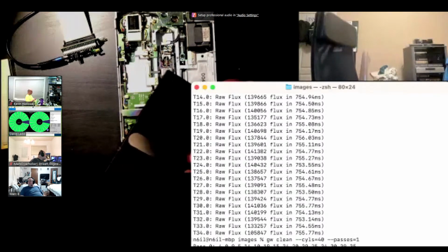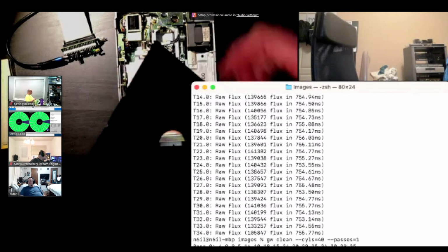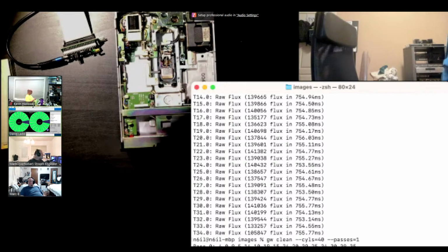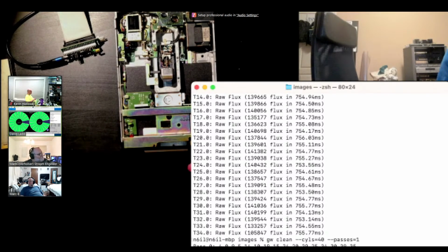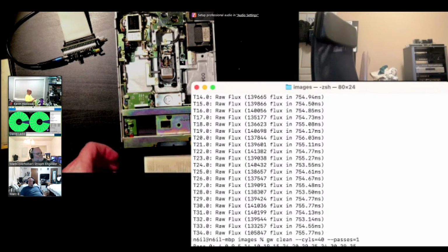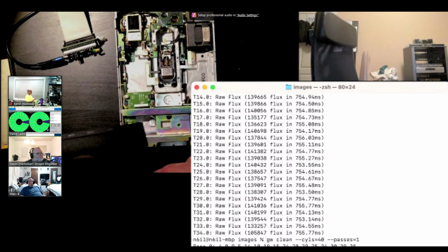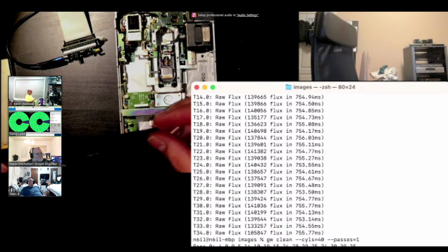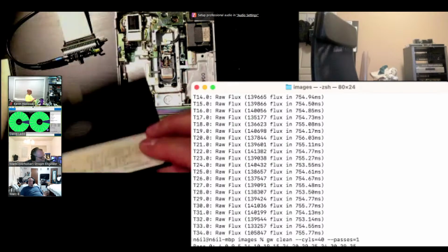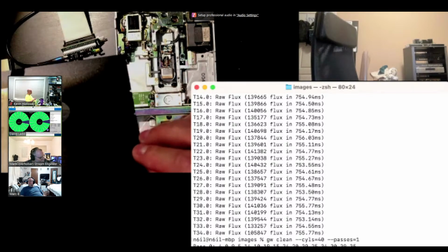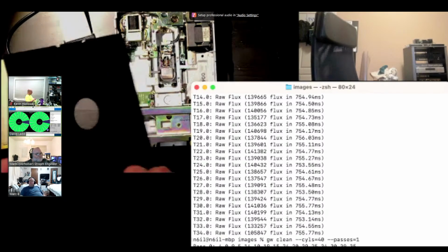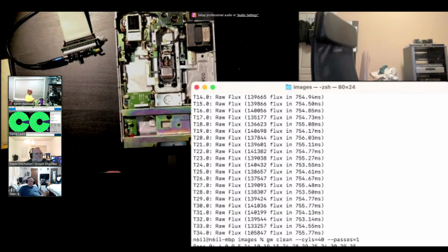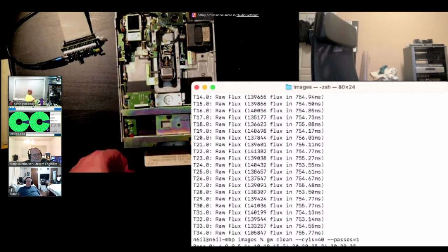Mine's latest firmware, which is 1.4, right? Yes, but depending on the original firmware that was written, the bootloader is normally a part of it, unless you're updating via the USB. Then the bootloader never gets updated. And sometimes, if there's been enough version differences, I'll manually do a full chip erase and then update the bootloader as well. But that requires the